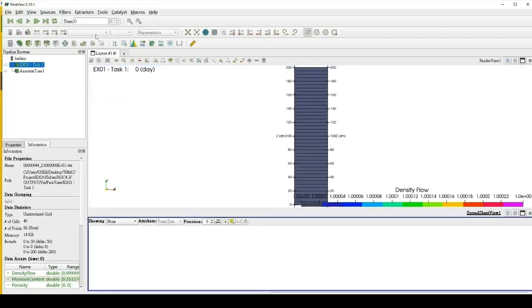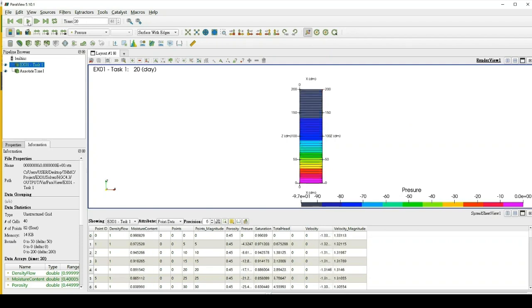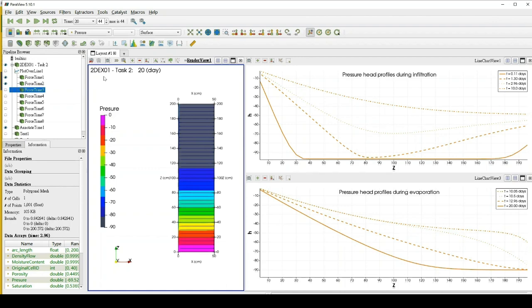Click the Open button next to PowerView. This section introduces basic concepts and utilities of PowerView for analyzing your visualized simulation results. The main visualization panel is located at the center of the window, displaying the colored mesh. Various toolbars are positioned at the top of the PowerView window.